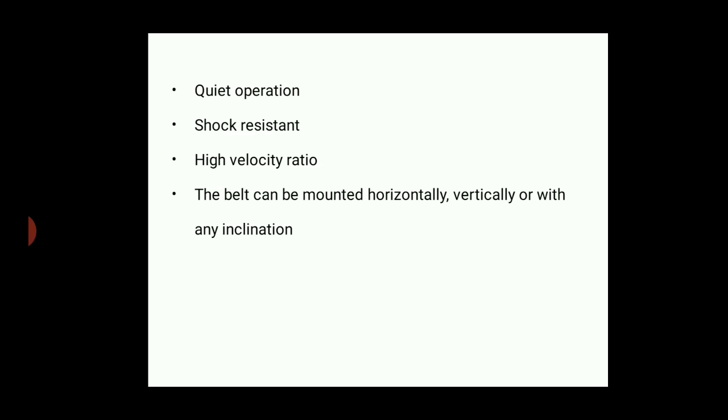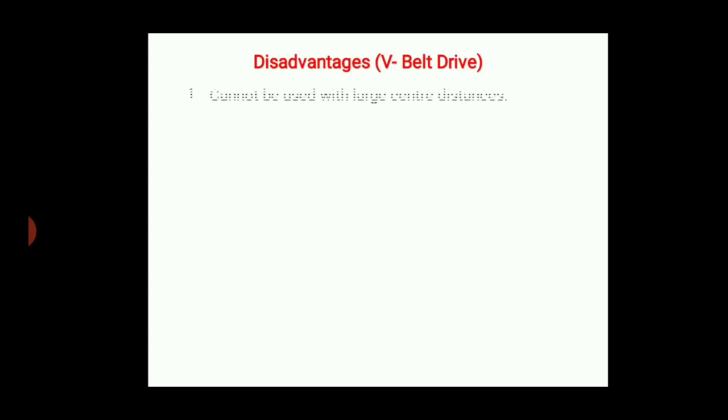You can mount multiple belts together on a single pulley, so that you can increase the power transmission capacity of a single drive. Then there are various disadvantages. It cannot be used with large center distances. Then the durability of the V belt drive will also be less as compared to the flat belt drive.